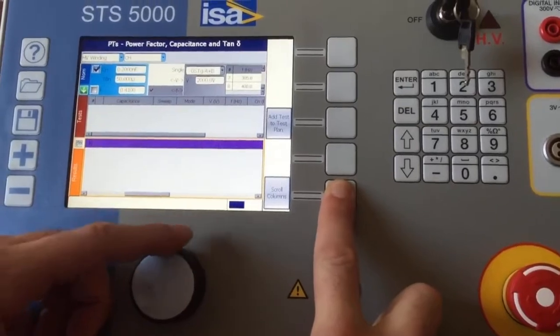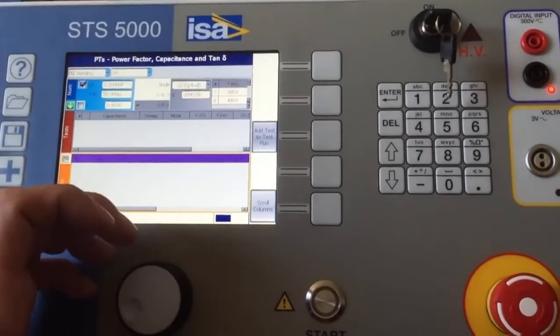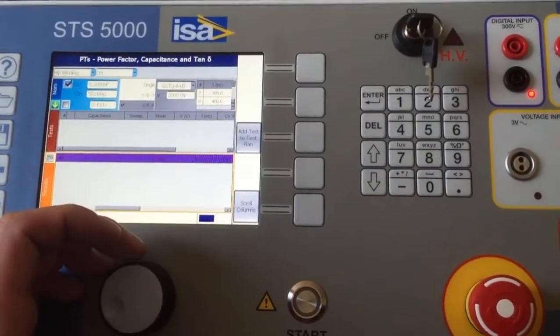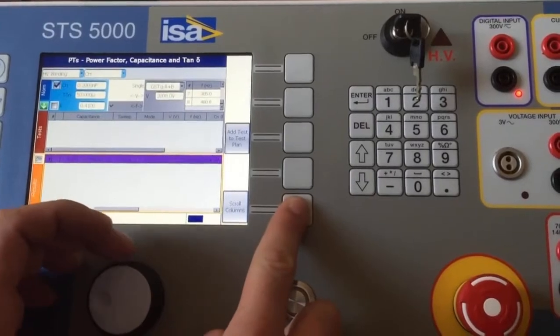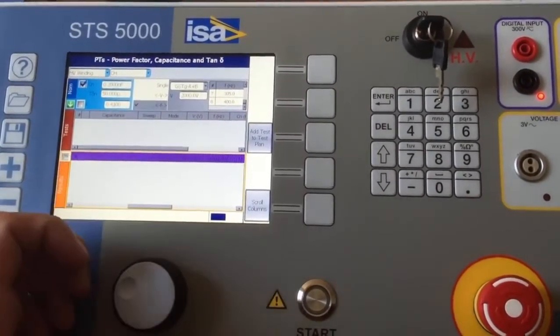here, because we are modeling right now the insulation as a capacitor connected in parallel with a resistor. You see a lot more information. So if you were to test a circuit breaker for tan delta, you would be looking at this information here.